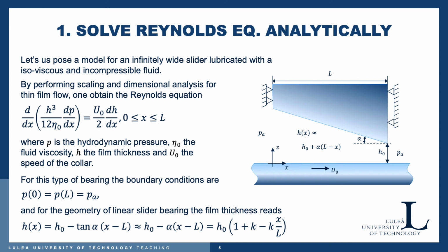Okay, solving the Reynolds equation analytically. This is possible if we have a problem where the lubricant, the fluid, can be assumed to be isoviscous, have constant viscosity, and have also constant densities. The fluid is incompressible with constant density.